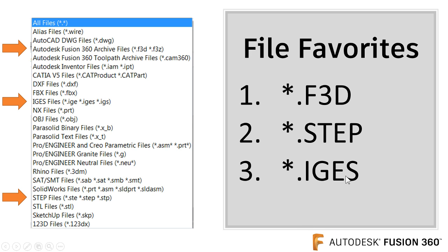And I've actually seen, with IGES and STEP, sometimes better results coming with IGES than you get with STEP. Because what happens in the background when you're bringing a file into your system, either a SolidWorks file or a STEP or IGES, and you bring that into Fusion, it goes through a conversion, right? It's a little bit like converting Danish to Chinese. There could be some errors going on. So whenever you receive a file from a customer that is not the native Fusion file, you should definitely spend 2 minutes investigating it, just to make sure that you got the right thing.